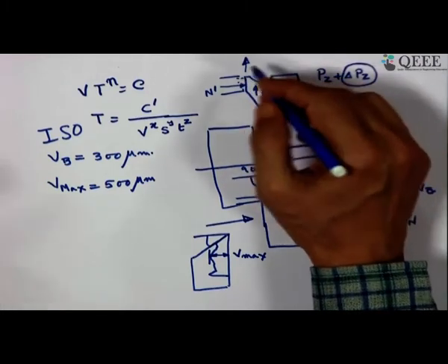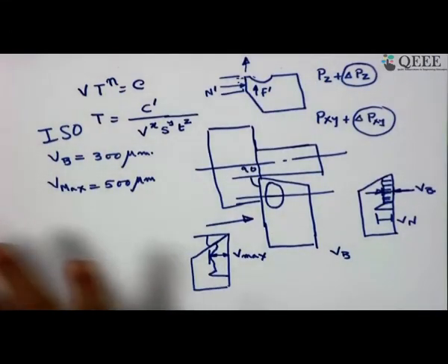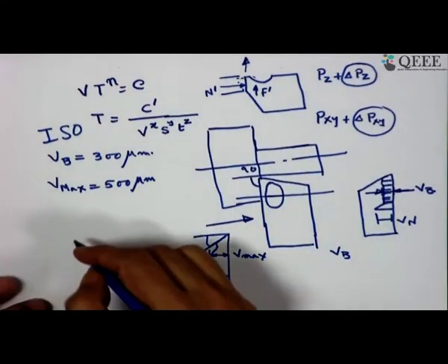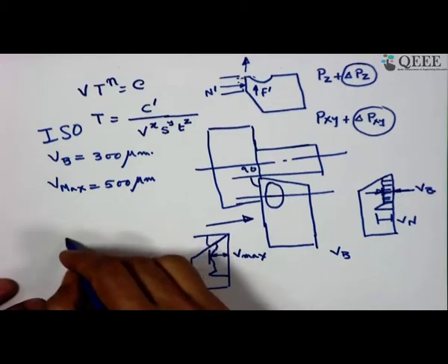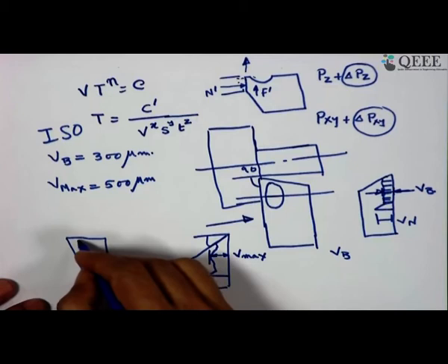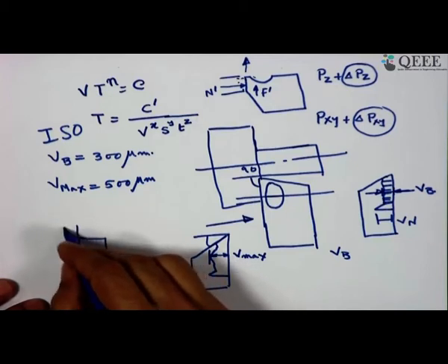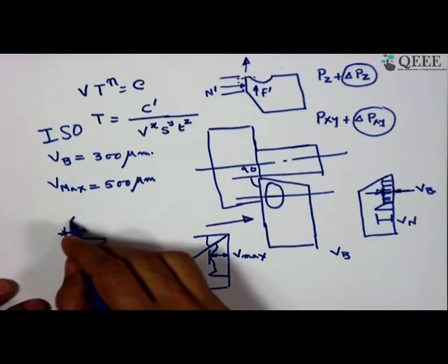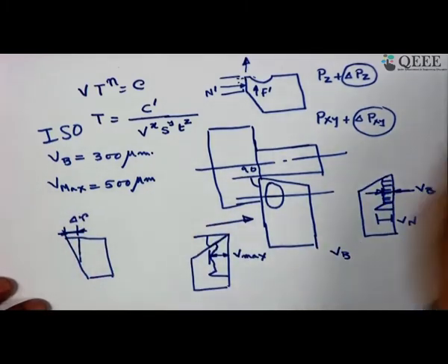One thing, in the very first slide, that was drawn, we have seen that this is the radial loss. So, this was the material, and when you have this radial loss, that means this one is out. So, this delta R, that means immediately our conclusion is your depth of cut will be less by delta R, and when it is less by delta R, you cannot expect to hold the same tolerance, and if it is a very tight tolerance, then you have to pay attention, even if you can go to 300 micron, particularly at the tip of the tool.